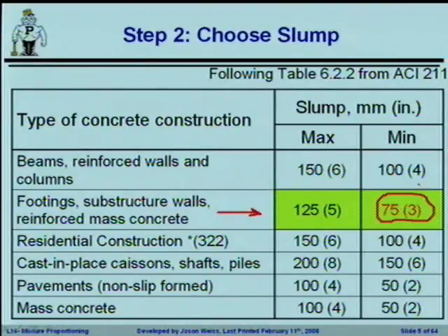There are concretes that are placed with a 0 or even what's referred to as a negative slump type mixture. Those are typically placed with heavy vibration and things like a slip form paver. There are other materials that have a very, very high slump because they're going to be placed in a region that's very, very difficult to get to. So you want to try to choose a slump that's appropriate for the equipment that you have available. For this case, I would assume that we would have something that would enable us to do a reasonable job placing the concrete.